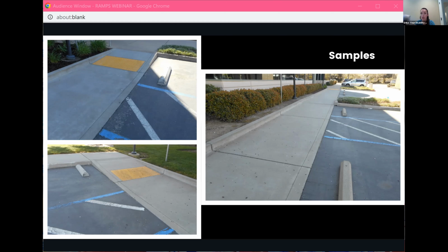Okay, so the next question is, if an accessible walkway is required to be 48 inches clear, but there is a parallel curb ramp, new section 705 says that 36 clear is required behind the domes. Does the 36 inches take precedence, or does the 48 inches need to be maintained without encroachment from the domes?